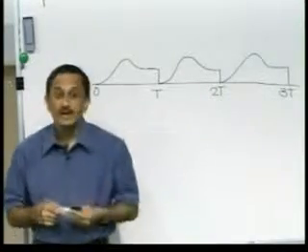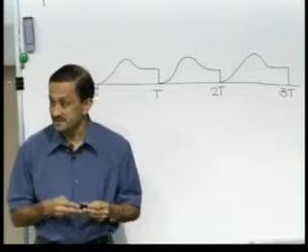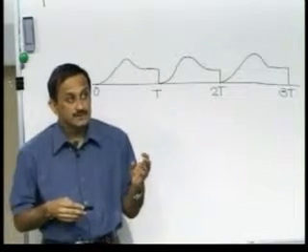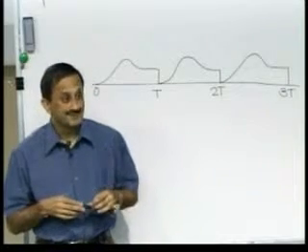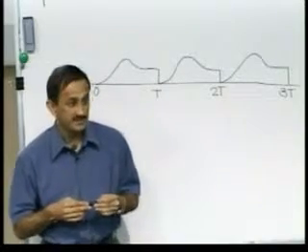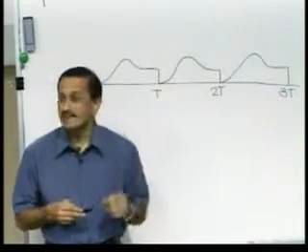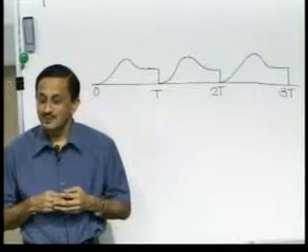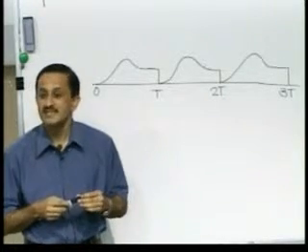In the laboratory, one often makes use of oscilloscopes which do not go beyond a few hundreds of megahertz at most, right? That is because a lot of components that we use in an oscilloscope are discrete components, and discrete components do not work beyond the range of a few hundreds of megahertz, in fact maybe not a few tens of megahertz at times. Now the reason why I brought this issue up is, one can exploit the idea of sampling to take the oscilloscope to capabilities beyond what its bandwidth can offer, and the idea is very simple.